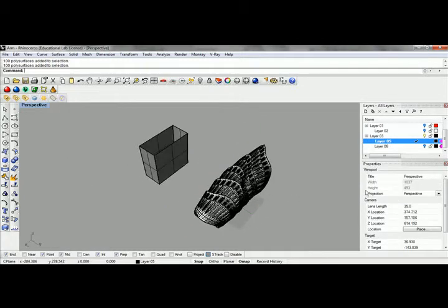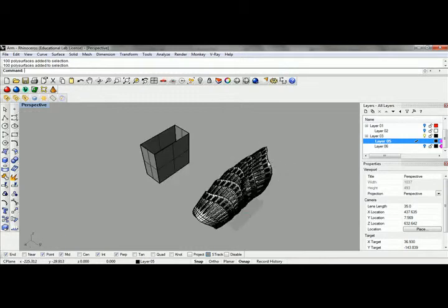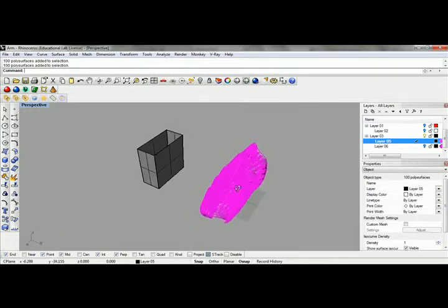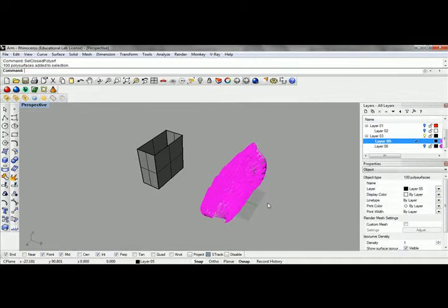All right. And so then the next thing I want to talk about here is actually getting this sent to a 3D printer. So say we've gone through and, like I said, I've already modeled this geometry. And so we know, or hopefully know, that these are closed polysurfaces. So the first thing we can do to test that is a select closed polysurface. You can see that right up here. Okay, and everything gets selected.